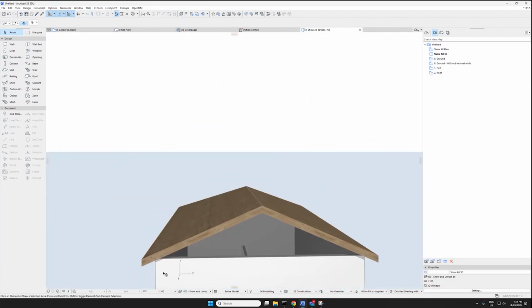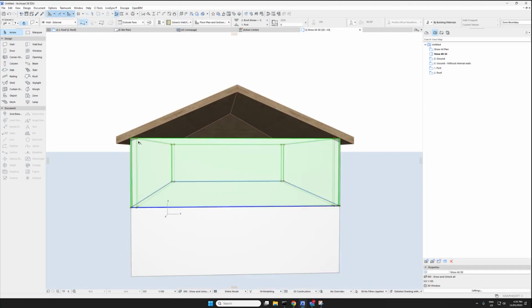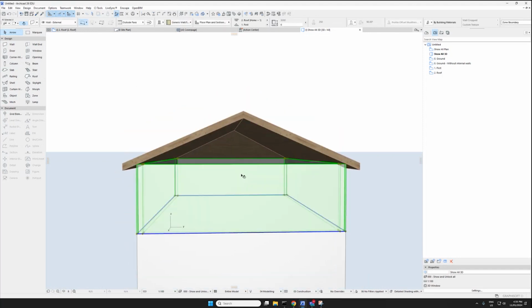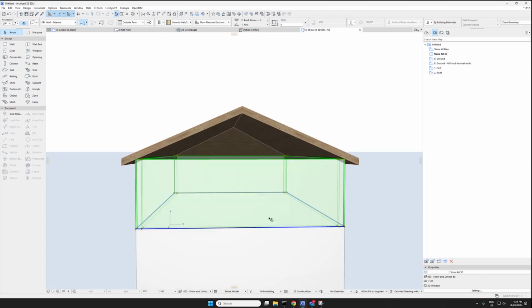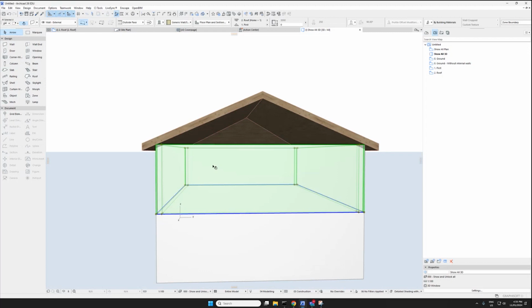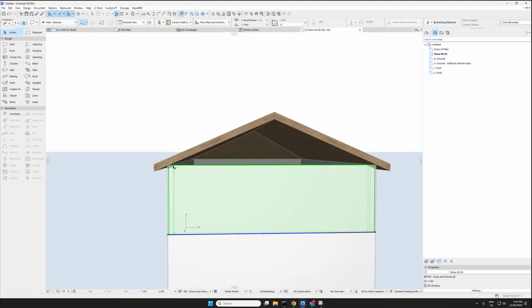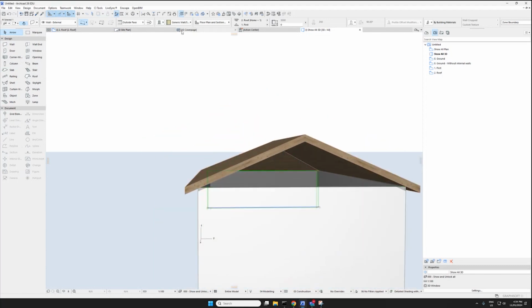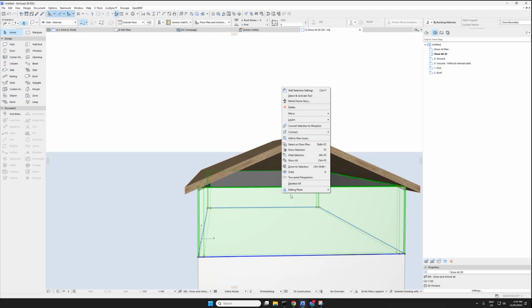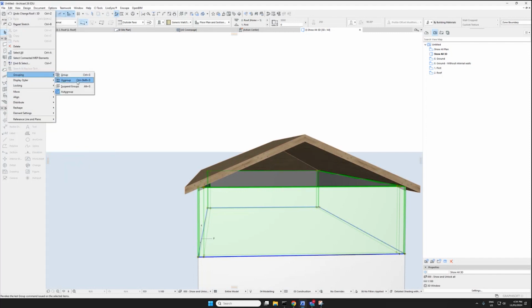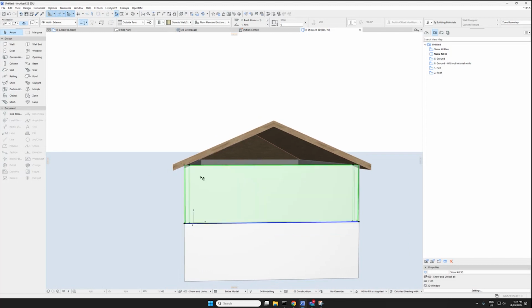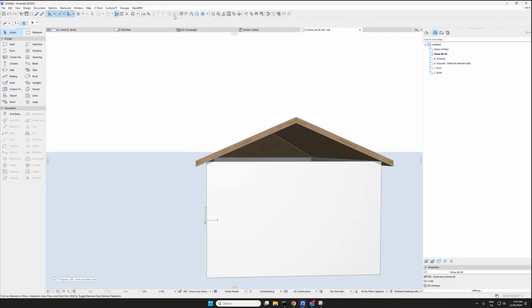Okay. So the custom plane was this gable end. So I want to extrude this up, for obvious reasons. So see, when I select the external walls, it's actually grouped it, and I only want to extrude this plane. The way I can do it is by Suspend Groups, up here, and that lets me select that individually. I could also go and ungroup it. So if I unclick this and right click, then I can actually ungroup it as well. Let me just go somewhere here: Edit, Grouping, Ungroup. Okay. However, it's sometimes good to have it grouped, and then you can just go Suspend Groups.